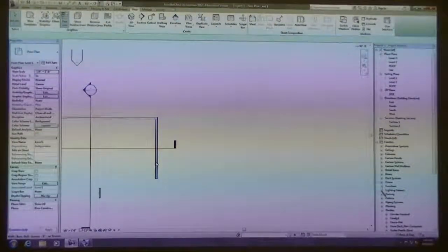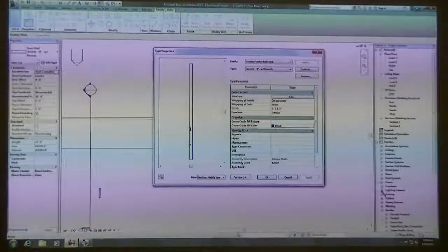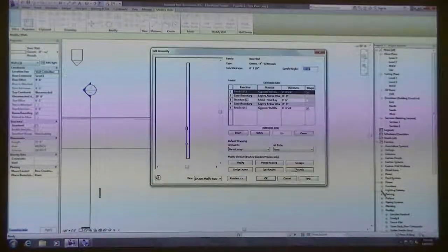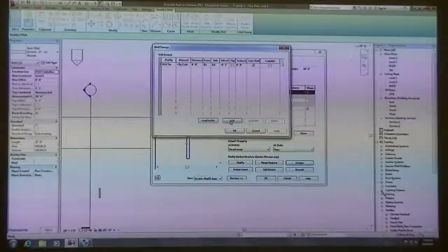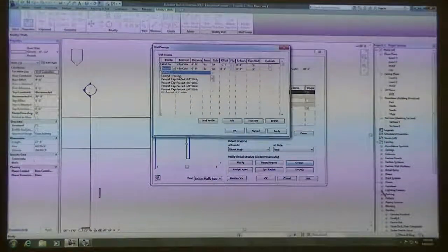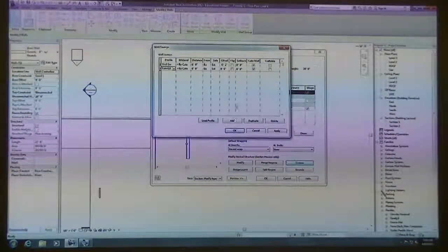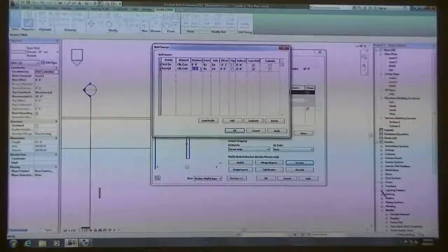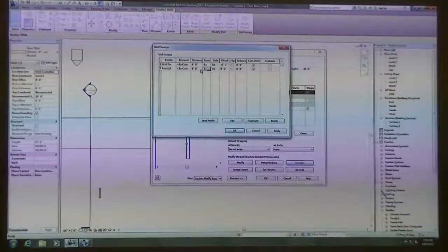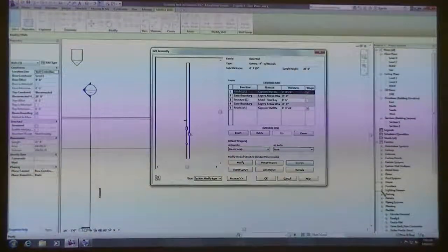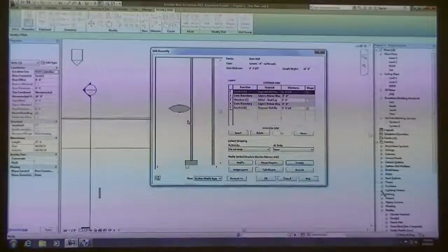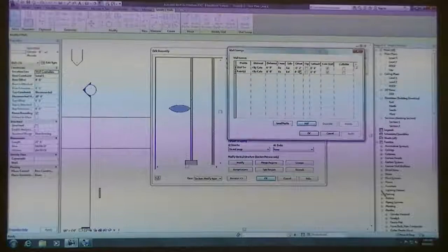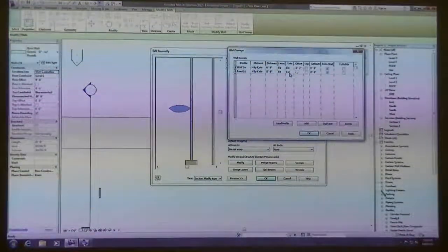we can then click on our wall and edit. And I should be able to go into my edit structure, click on sweeps, and add a profile. And when I do that, I should be able to select my family component. I just called it family 1, I didn't save it, so. And maybe I'll put this 8 foot up. So you can see I've got my little football sitting up here. And maybe I can make it engage the wall a little bit more. Do something like -2 inches.